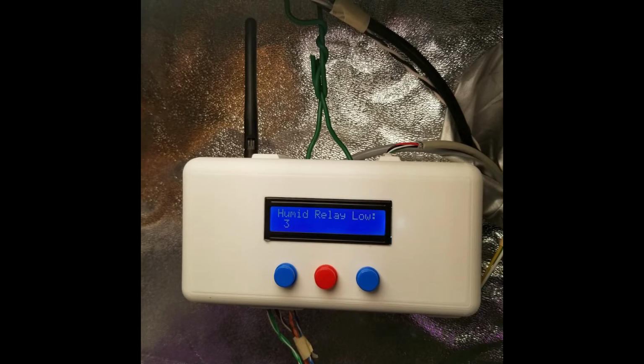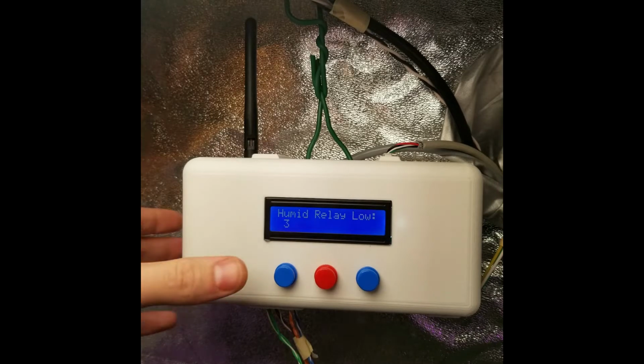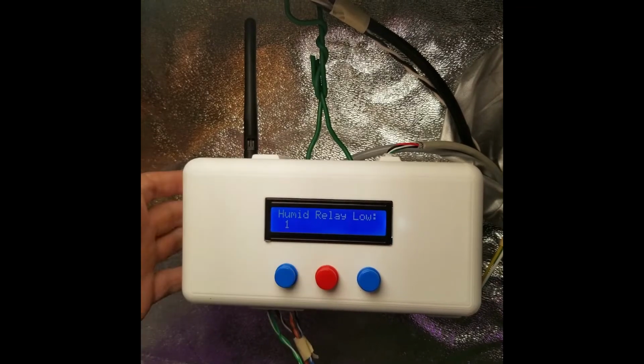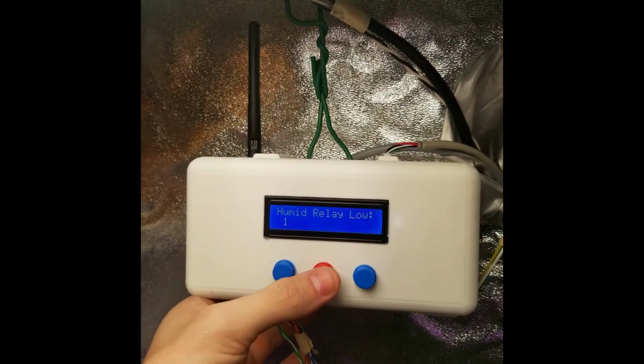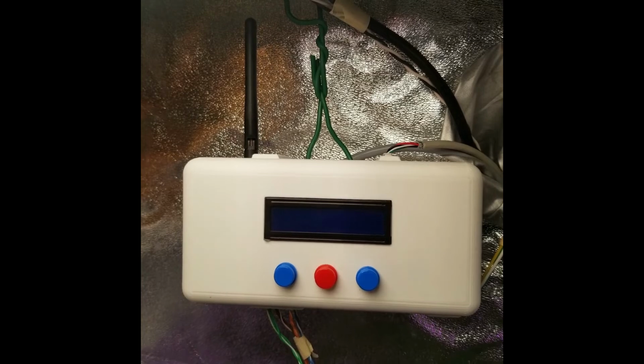Say the upper trigger is set to 60, this one right now is at 3. It would be 60 minus 3, so the lower trigger will be 57. And then it would be 58, 59, etc. And then the last button press will just turn the screen off. It also features an auto timeout feature for if the buttons are not pressed. And that is the bulk of how the transmitter works, so moving to the receiving module.